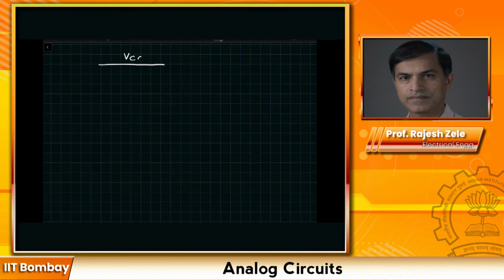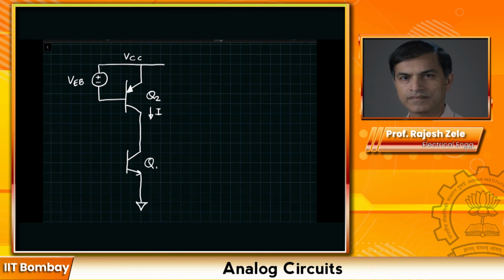This is your VCC, and you start off with your PNP transistor and you apply some constant bias here, VEB, such that the transistor Q2 is in active region, which will give you current I, a constant current source, flowing, and that is going to be flowing through our Q1.